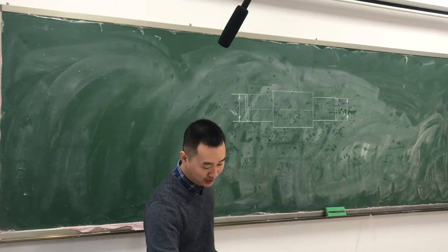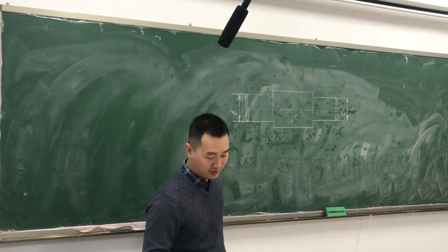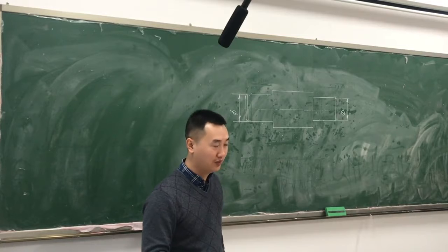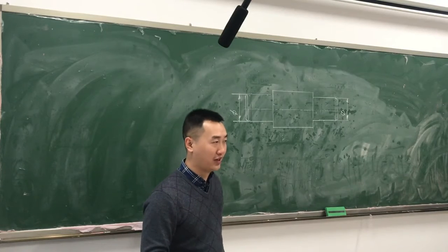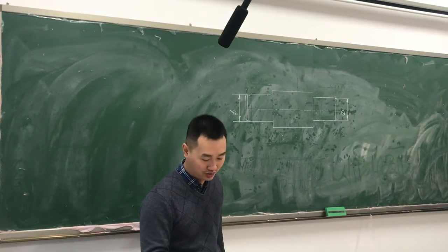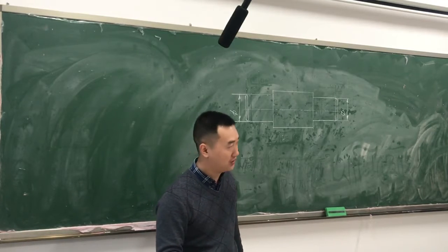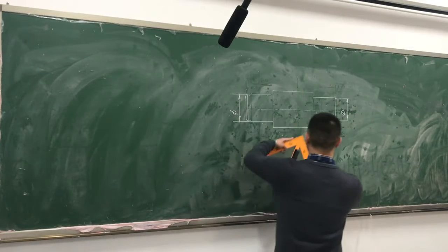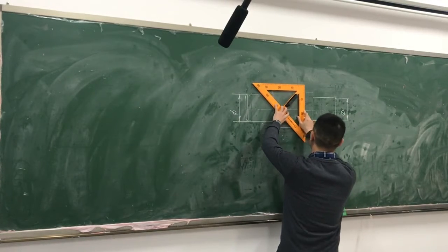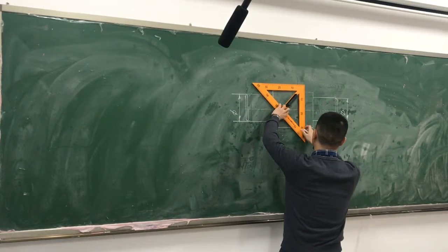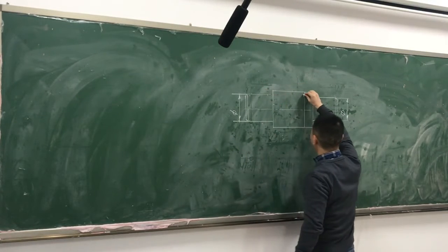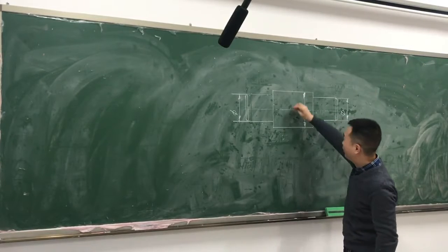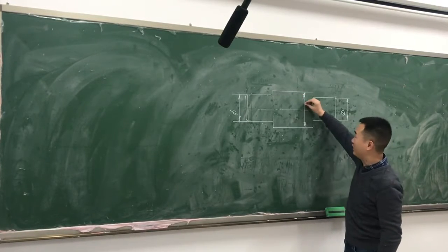originally the lead line is at the place as the extension of the dimension line. So this is not correct, right? The lead line should not be at the extension of the dimension line. So we need to change the dimension line from the original place to another place. The dimension line originally is here, and we change it to here.